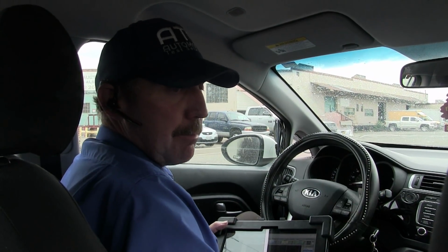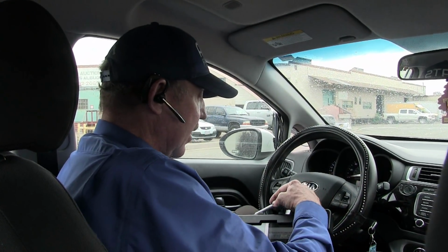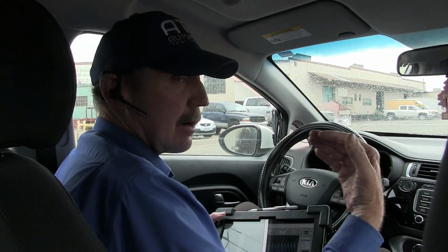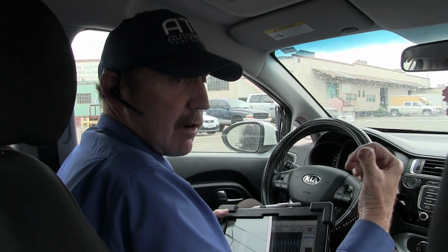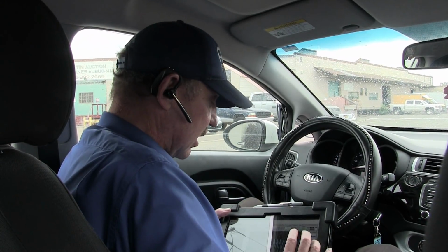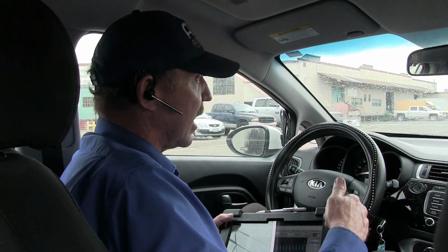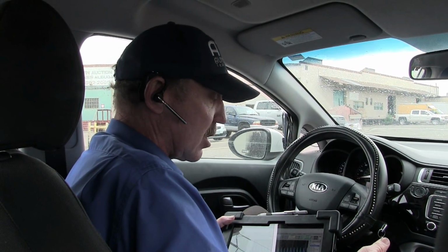So if you went and put a new pump in this, you're not going to fix this car because that pump is good. This has some other problem. There's some kind of restriction in the line. From the pump to the engine, there's a restriction. So that's what I see here, guys. And that also backs up the data that we first got when we first drove the car with a scan tool. We were losing fuel pressure.